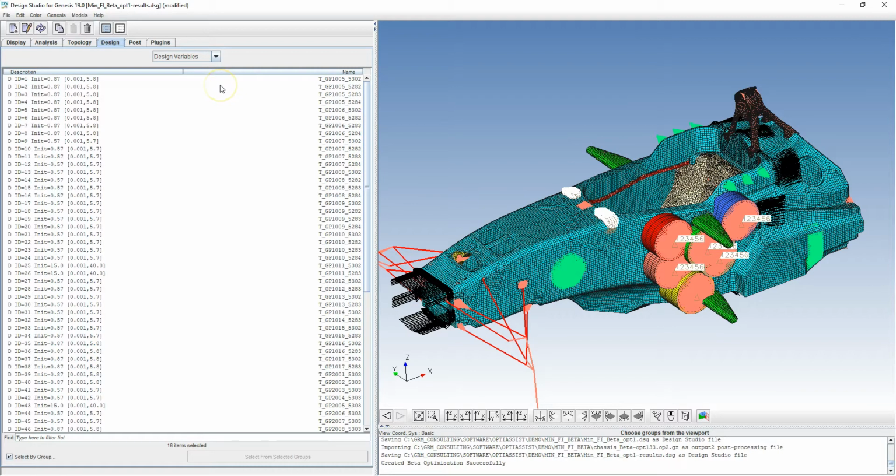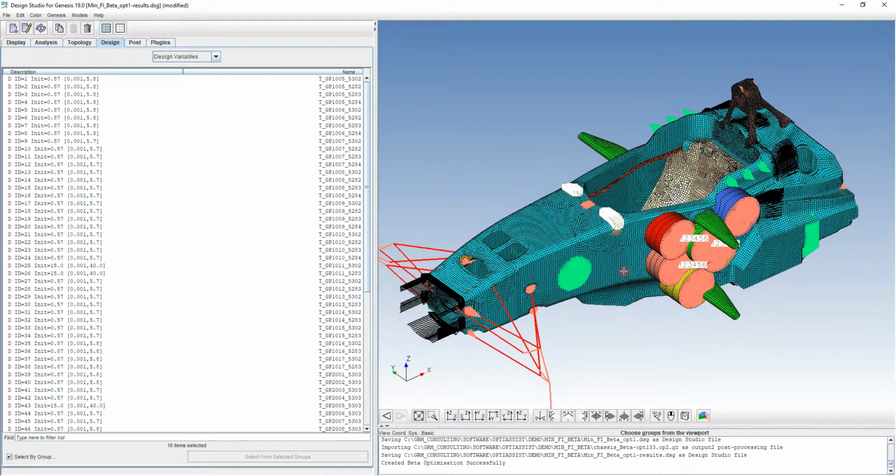Okay, so that is the setup. It's as easy as that. I will go ahead and run this. Be aware that anything that has this many failure index constraints needs to be running on a large model, and we really want a large computer system, ideally Linux, and be prepared it will take a fair few hours to solve. Okay, so I'm just going to pause this whilst I run it.